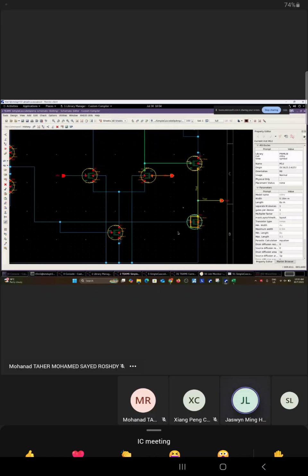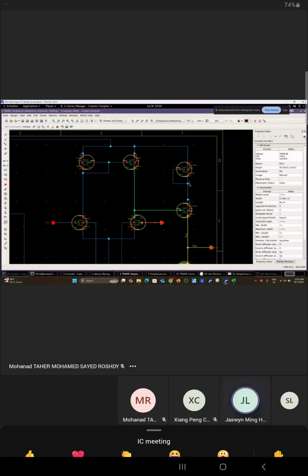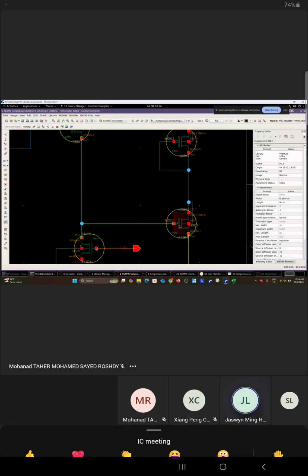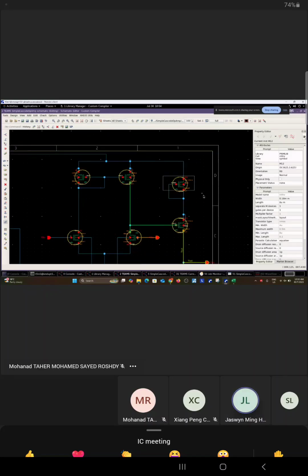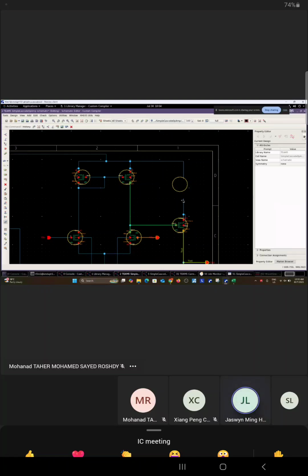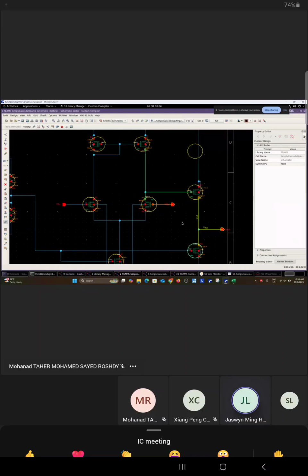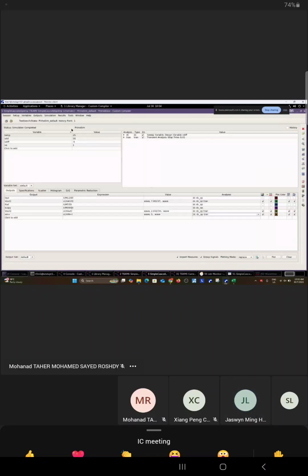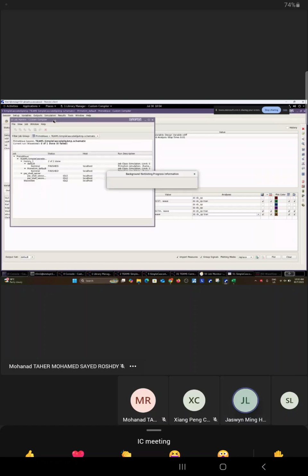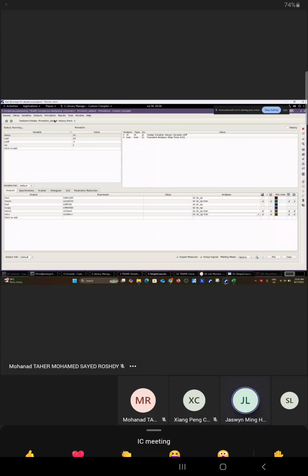I think you can go up here. This one. Oh, you have another. I don't think you need this one. Yeah, remove it, this one no need already. Because this introduces a drop in VDS and another one introduced by this one. Let's see first. Try to run again, then we try to tune. I think it does not solve the problem entirely. We need to fine tune again.